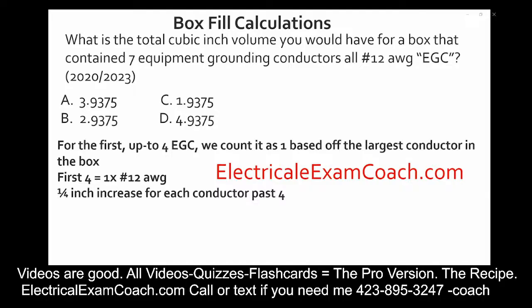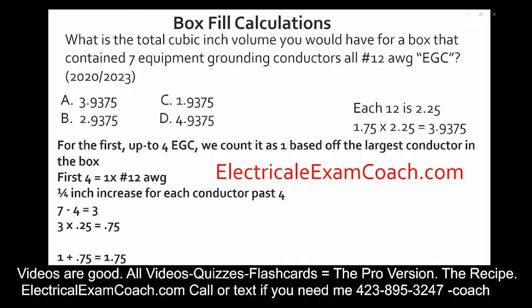Sounds complicated. We're going to break it down very simply. We have 7 total, and we're going to minus 4 because those first 4 we counted as 1. So we have 3 left over, and we're going to take those 3 and multiply it by 1/4, and that gives us 0.75. So we have a total of 1.75 conductors based off whatever the largest conductor is in the box. In this case, there's only number 12s. So we would take that 1.75, multiply it by the cubic inch volume for a number 12 conductor, and we end up with 3.9375 cubic inches for our equipment grounds.